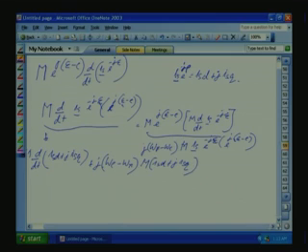So all the voltage terms we have brought into the real and imaginary components. We have to separate out the real and imaginary components. Then we will get the real and dynamic equations in the DQ reference frame, the real and imaginary components for the stator and rotor. So let us do that one.